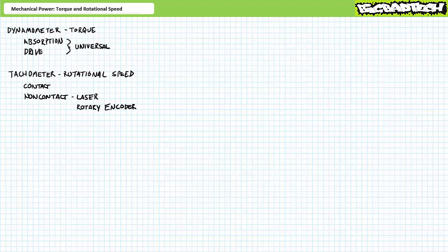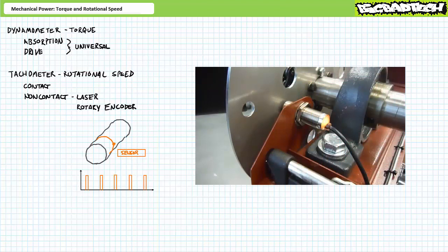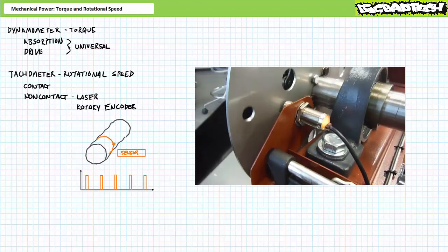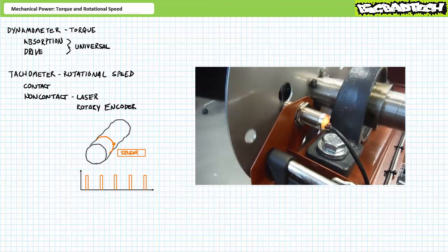You don't need to pay some unschooled youth $8 an hour to sit there with a laser tachometer to get valid rotational speed readings, because there are numerous automated methods of doing so, all falling under the blanket term rotary encoders. If all we're concerned about is rotational speed and not direction or position, a single Hall effect or inductive sensor on a shaft is more than sufficient to do so. Every time an indicator, the presence or absence of a metal object, passes through the sensor, it detects the presence or absence and indicates it with a pulse, hence the term pulsar.